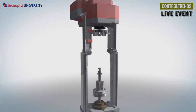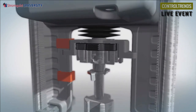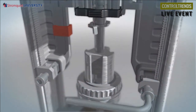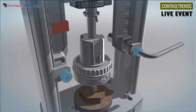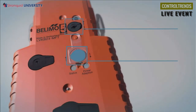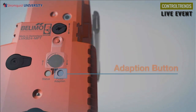Slide the actuator down the linkage riser until the valve stem and the coupler click together. Slide the coupler lock down. Tighten the actuator and the linkage riser using the 2 screws provided. Note the teeth should line up. Set up the direction switch and fail-safe switch in the desired position. Power up and push adaptation button.